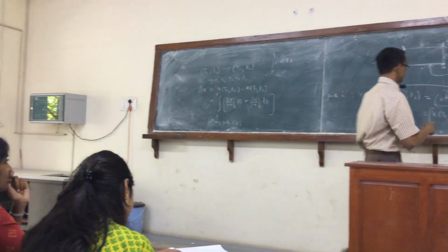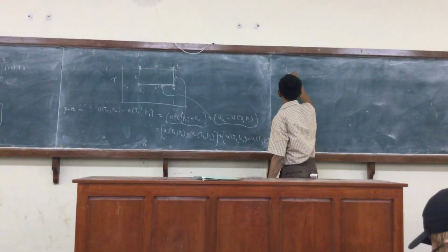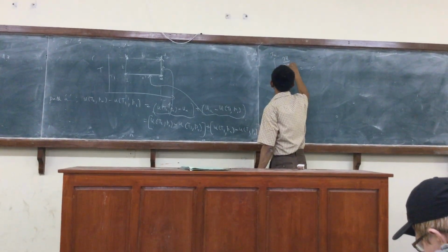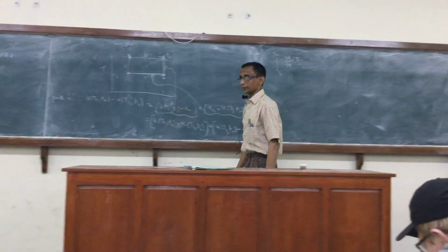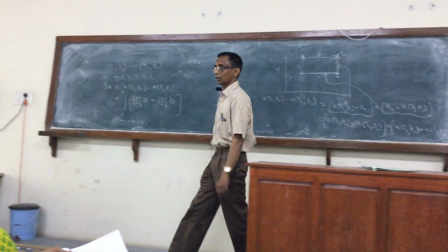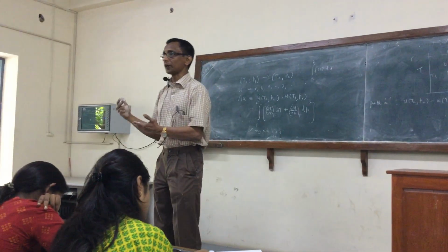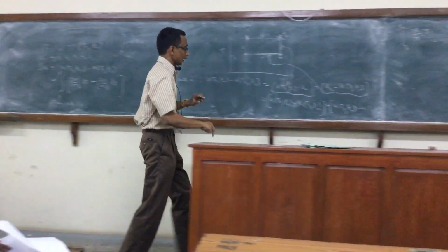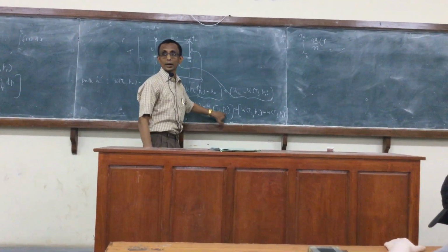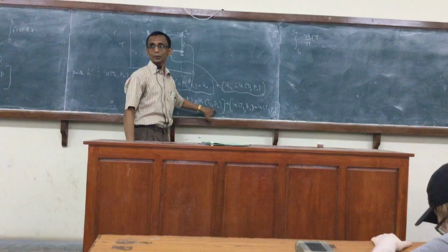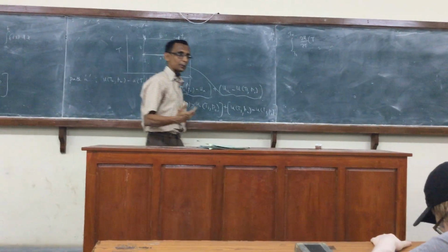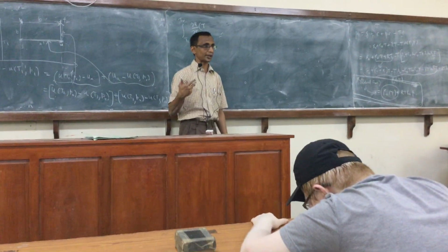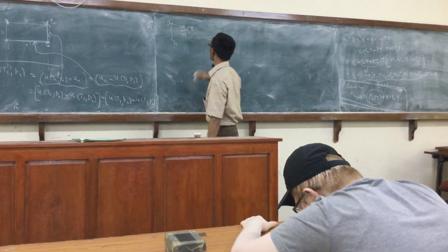right? So I will write this integral as integral T1 to T2, du by dT, expressed as a function of temperature. Of course, du by dT is a function of temperature and pressure, but for this integral, the pressure is fixed at P2, and I need to mention that because the property is a function of both temperature and pressure, so it depends on which pressure I evaluate, so I cannot just suppress that.